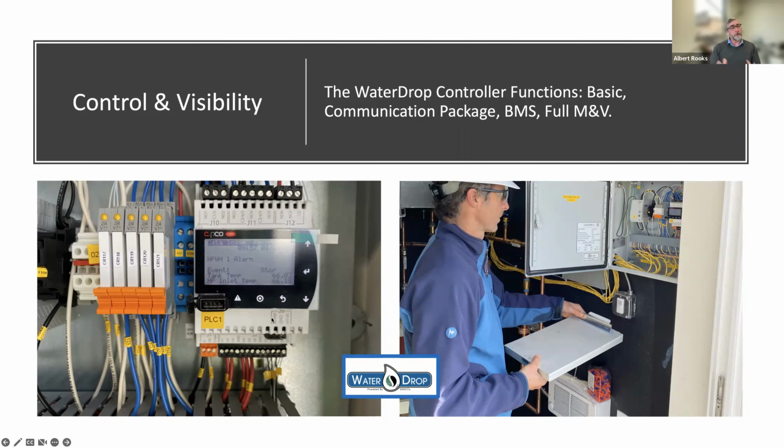All of those heat pumps are controlled by this controller that we build in-house, and we have a wonderful guy named Peter on site starting it up. Essentially, the control is going to operate the heat pumps based on the input of the conditions of the plant. It's going to look at the temperature of that primary storage. There'll be a thermistor midway up on the primary storage.